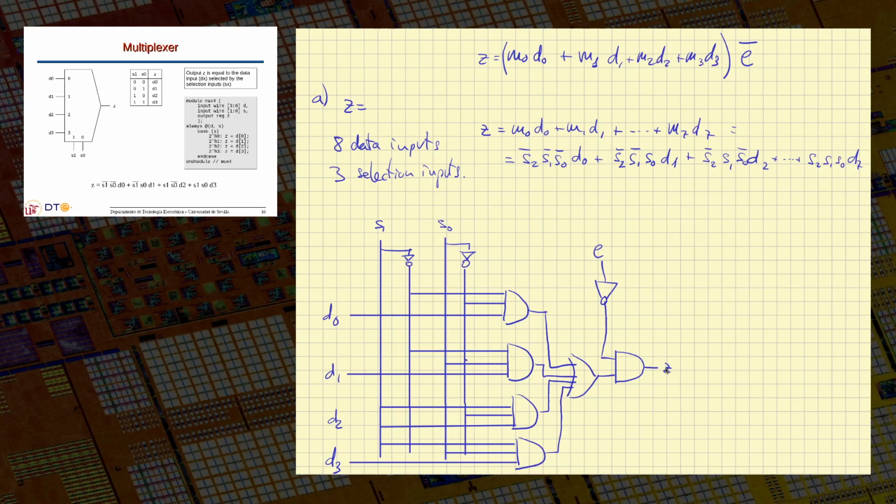It's not really very convenient, because by adding an additional AND gate, we add an additional level of gates to my circuit. Before, we had complements, gates, and the output. We had a regular 2 levels circuit plus inverters. Now we have 2 levels plus a 4th level here with this fix.